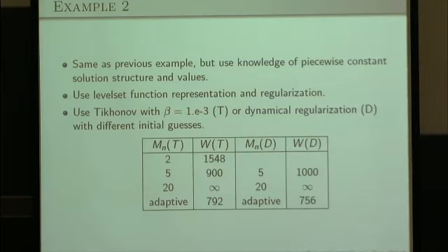Before, 20 PCG iterations at each outer iteration was very good. Now suddenly it diverges. In this case, you're trying to solve a singular system too well, so it doesn't work at all. Whereas 5 is a good number, but the adaptive algorithm is better even than 5. The point is that the adaptive algorithm finds the right thing without trial and error.